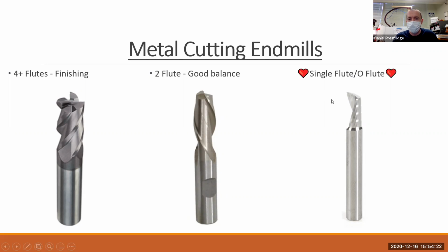So if you're doing facing passes, which is just going over a workpiece and trying to make sure that the top part is flattened, once you step over, which is going over to your next part, so if it goes this way, the next step, how much it moves over is your step over. With those, there's only one flute on it.